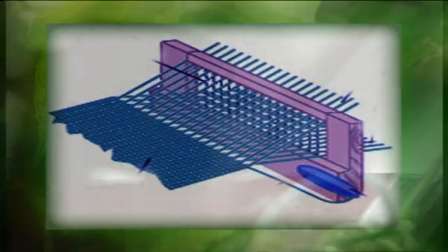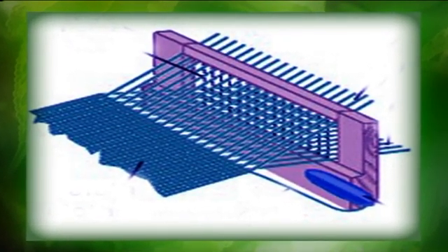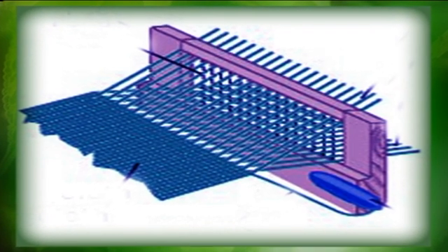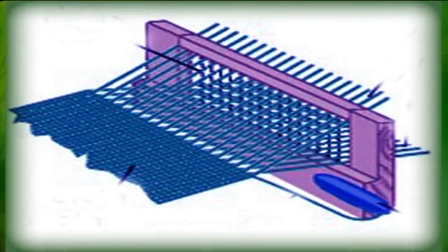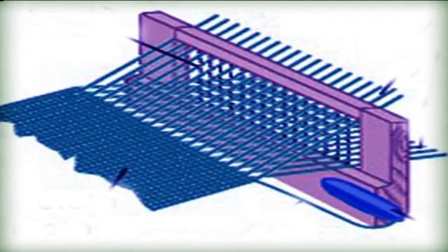It is the process of separating the warp threads which run down the fabric into 2 layers to form a tunnel known as a shed, and the shed is produced by means of heddles. Sheds should not be too large but sufficient for the shuttle to pass through comfortably without excessive frictional resistance.